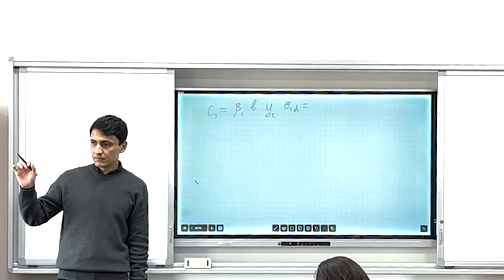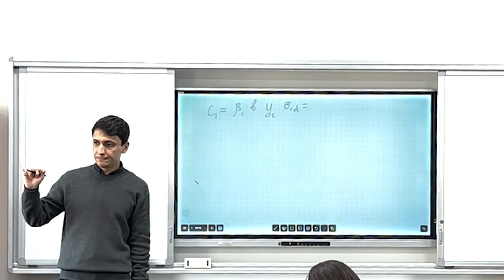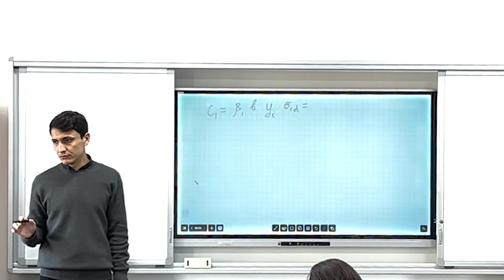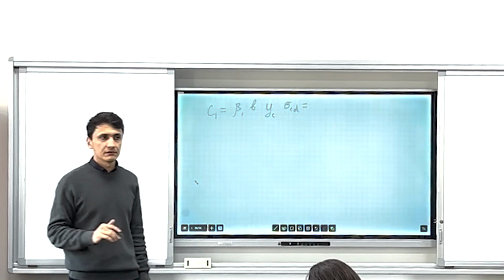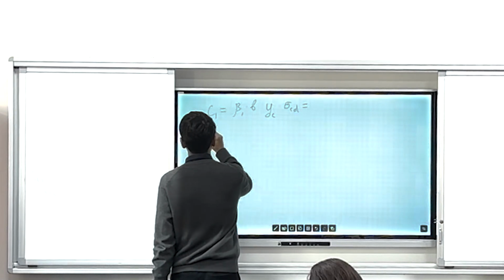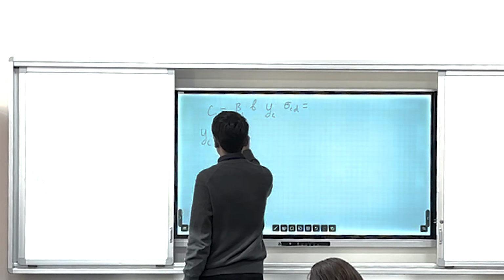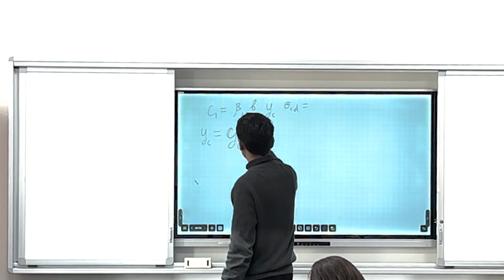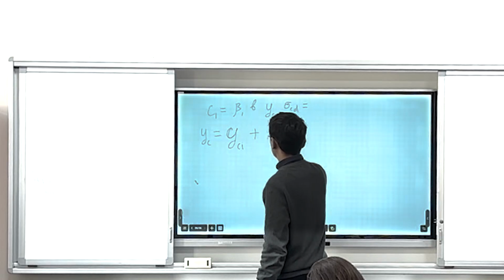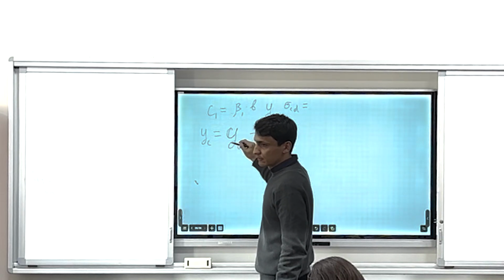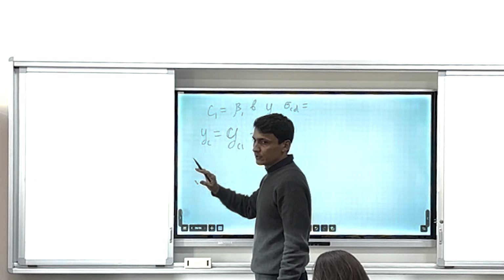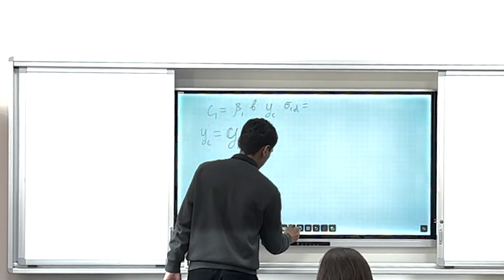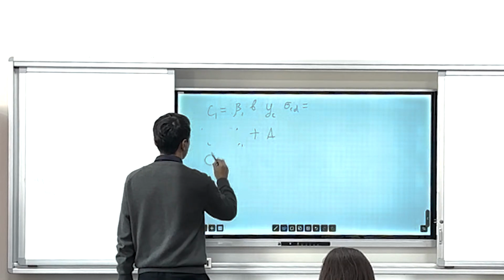If it's not correct, you substitute a new value for YC and repeat the calculations. But you will not just substitute: the next YC will be calculated as your first YC plus the value that should be added to YC. So you will change your YC based on the error you have. Only the first step is an assumption.